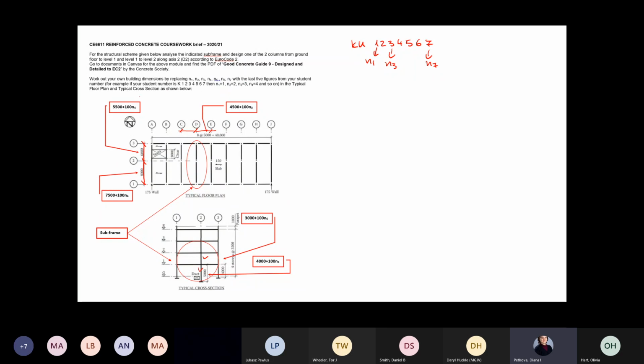Okay, so as far as this page of the brief is concerned, things are very straightforward. Yeah. So we'll assume that these slabs are one-way slabs. We don't have indication that we have a beam anyway, so these are very rectangular panels. The ratio here will be greater than 2, so it is a one-way slab, and we'll probably work with at least the minimum thickness of the slab of 150 mil. Okay.